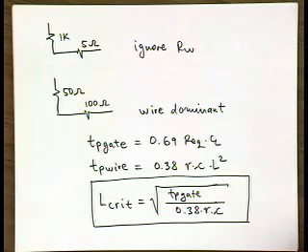If the rise time at the input is smaller than the RC delay of your wire, then the wire becomes dominant in the delay calculation. So the first rule is to make sure that your length is higher than the critical length. The second check is whether the rise time at the input is sufficiently small compared to the propagation delay time constant of the wire; if so, you need to include a distributed model to be accurate.